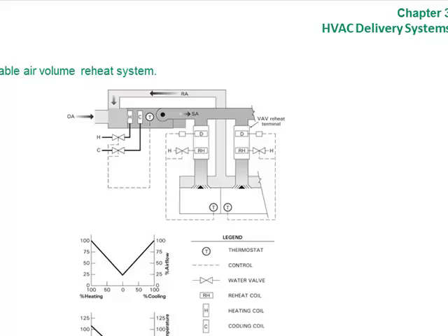If you need to control the humidity but have cool air at the same time, you have to use this system. So that has airflow and heating in it, and then the thermostat here, and then you have a damper, and then over here you heat it up again because you're controlling the relative humidity, or the reheat coil. That's what it is.